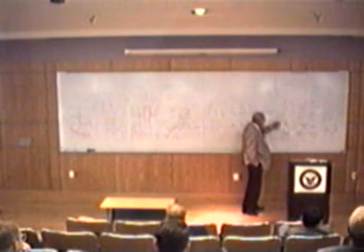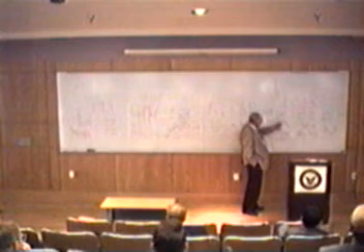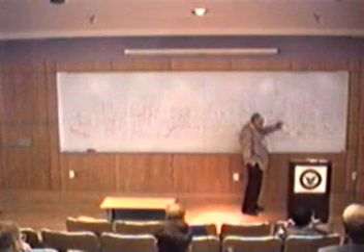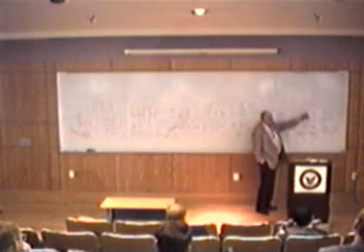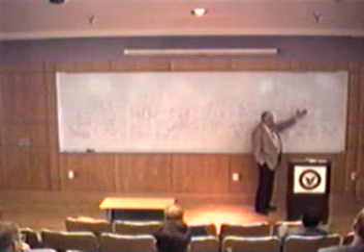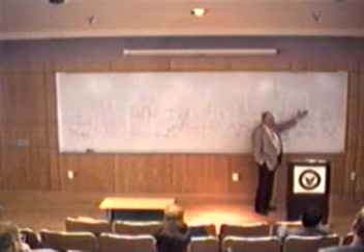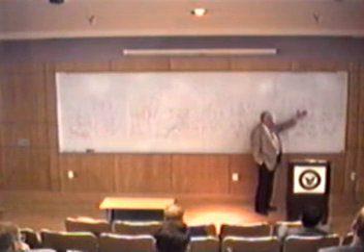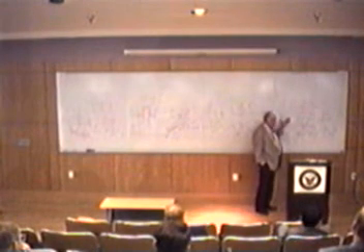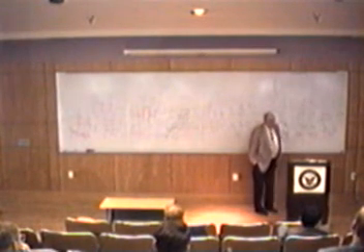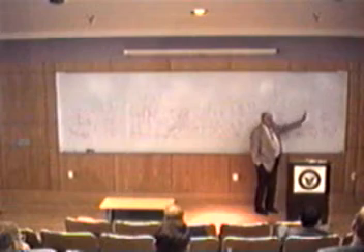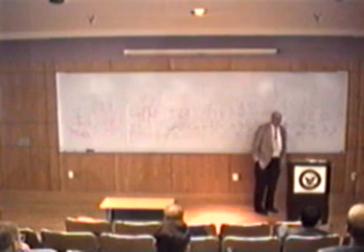It is taking the interval, the delta t sampling size times the 2n number of samples you take, that period, and everything is forced to be harmonic in that. You may have a perfect sinusoid, perfectly periodic, but if it isn't that period, you'll find it spread over the spectrum. More strongly nearby, but you'll find it spread over the whole spectrum.